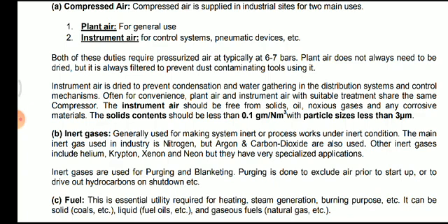6 to 7 bar. Plant air does not need to be dried air, but it is required to be filtered to prevent contaminating the tooling using it.